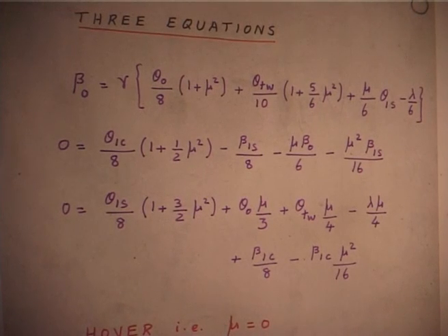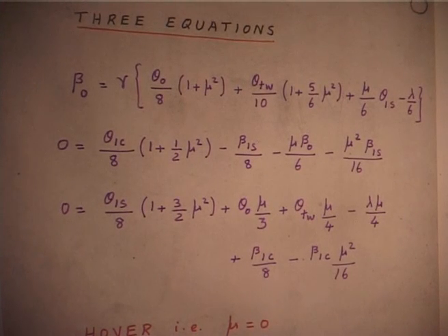That is what the trim analysis is. The entire trim analysis is related to iterating between flap motion and then fuselage equilibrium. So, you have to keep going back and forth, that is why it is a complicated analysis, okay. Even the solution procedure is a little complicated. This is a very simplest, that is what I am showing.